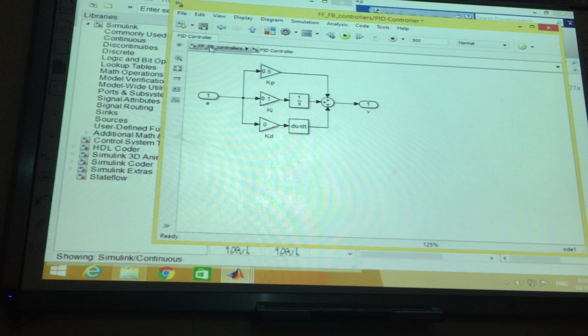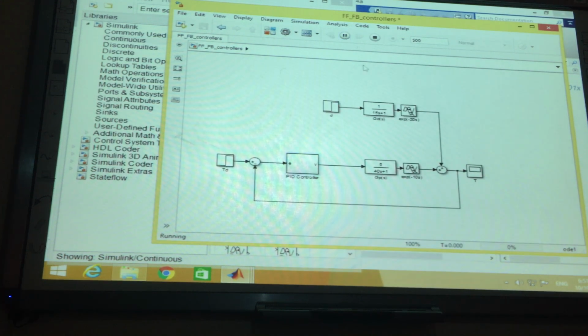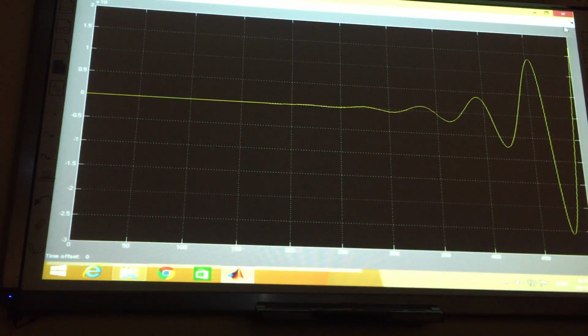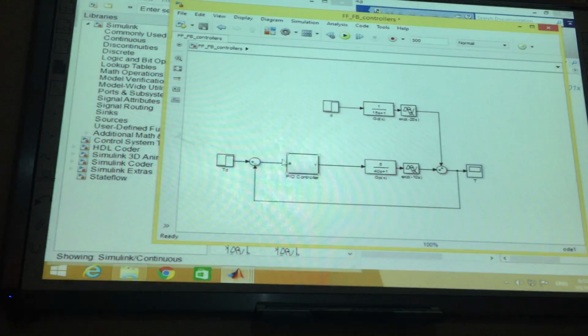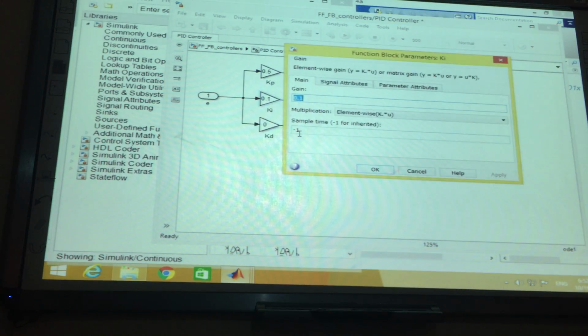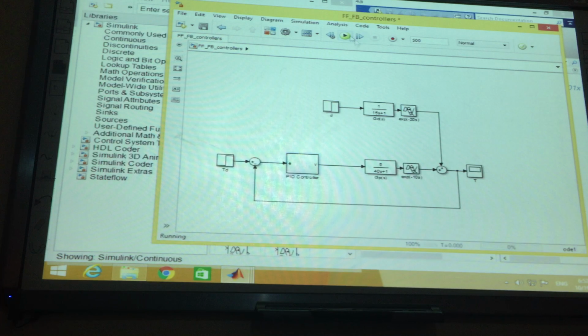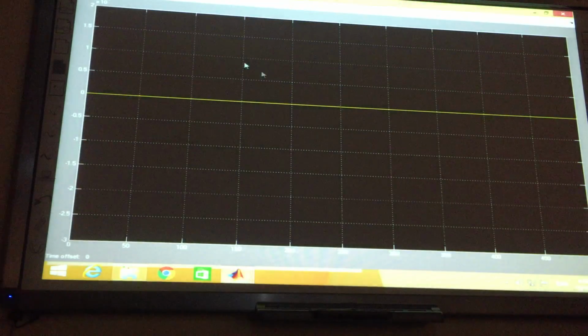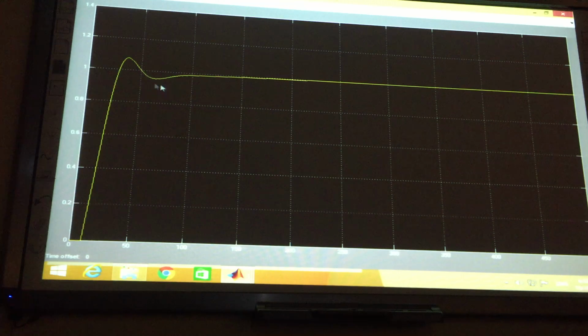We can find the exact values using Ziegler-Nichols. It's better. You have the Ziegler-Nichols method, with which you can find all of your parameters, right? But let me just do it by trial and error right now. No, you have to design them using the Ziegler-Nichols method. You have tau, you have L, you can go to the table and get the PID controller parameters.